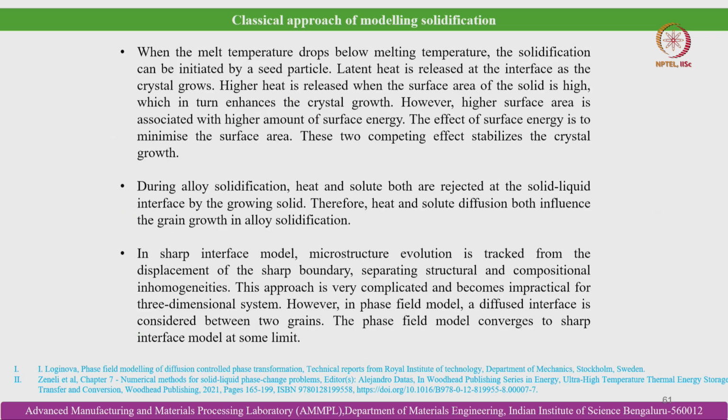Moving ahead, when the melt temperature drops below the melting temperature, the solidification can be initiated by a seed particle. Latent heat is released at the interface as the crystal grows. Higher heat is released when the surface area of the solid is high, which in turn enhances the crystal growth. However, the higher surface area is associated with a higher amount of surface energy. The effect of surface energy is to minimize the surface area. So these two competing effects stabilize the crystal growth.